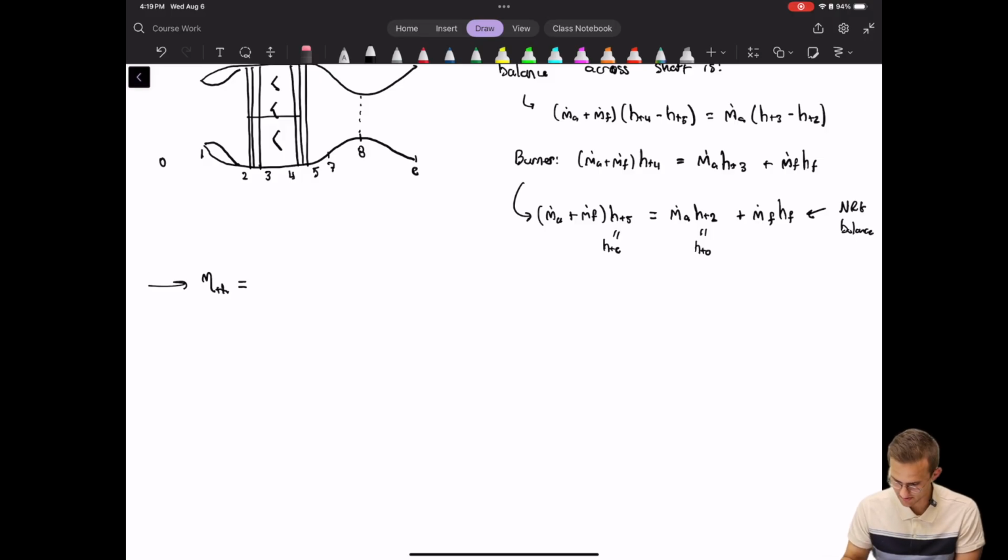I can't remember the actual definition right now. Actually, I think it was jet power divided by the amount of heat injected due to combustion. And then we wrote the V squared term in jet power by splitting it up into the total enthalpy and then the static enthalpy. You can go back to that lecture to make sure I'm not making a mistake here.